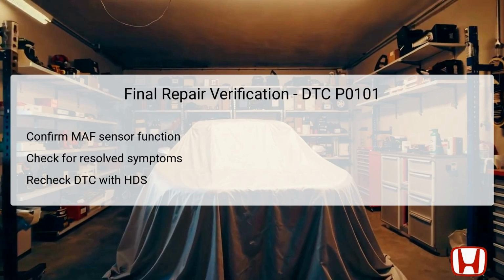After completing all necessary diagnostic checks and repairs for DTC P0101, it's essential to conduct a final repair verification. Start by confirming that the replaced or repaired MAF sensor is functioning correctly. This can be done by rechecking the corresponding signal values using the HDS to ensure they align with expected parameters.